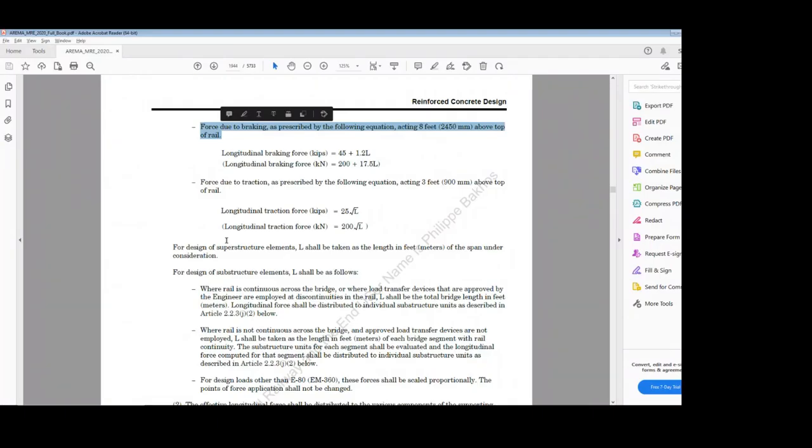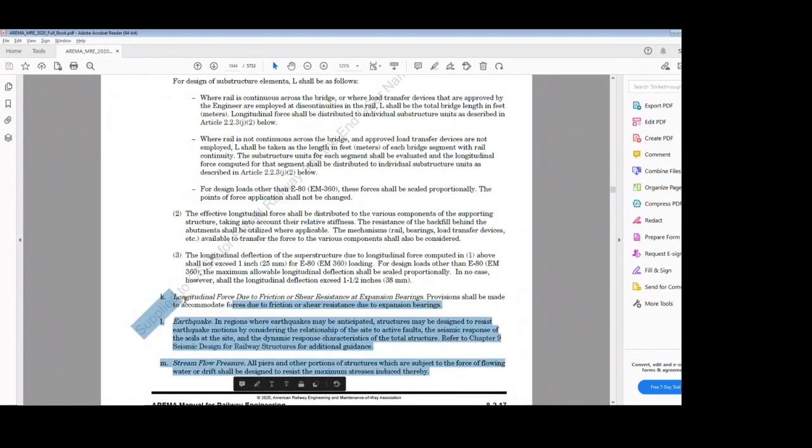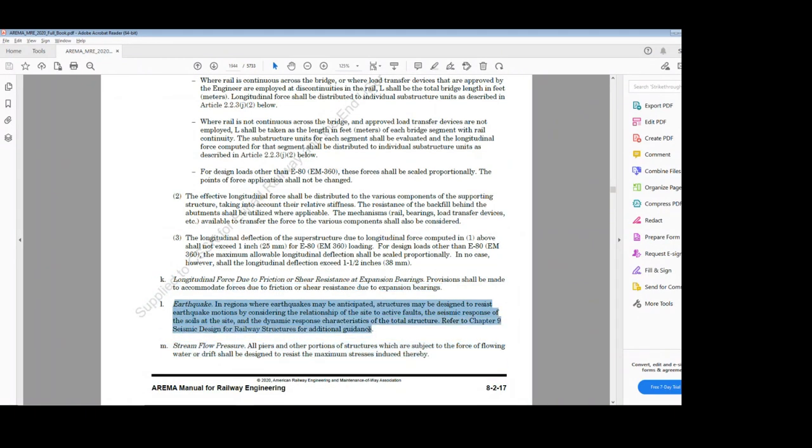Now moving to the next one, the earthquake force. Here in Tanzania lot 5 or lot 6, we will apply this earthquake force by European standard. It is given in the DPR only, so we have to apply this earthquake force as per European standard. But earthquake force is nothing but mass into acceleration. Simple. Earthquake force equals seismic acceleration into seismic mass. So whatever seismic mass is present at the time of the earthquake, we have to multiply it with the seismic acceleration.